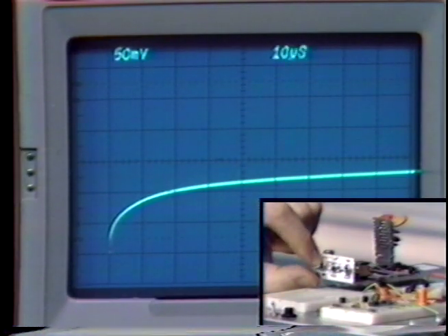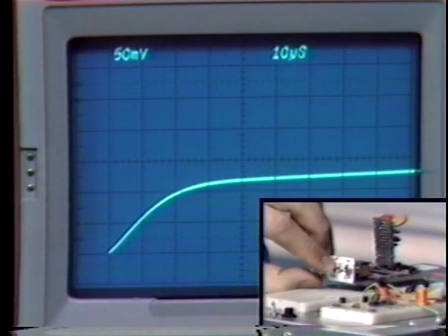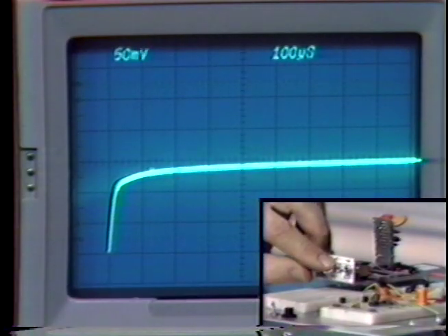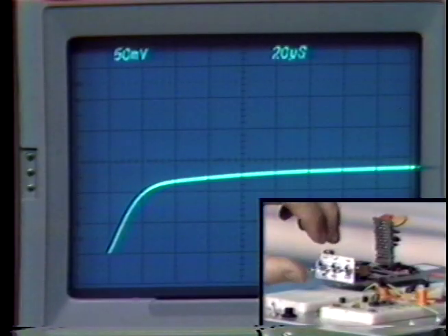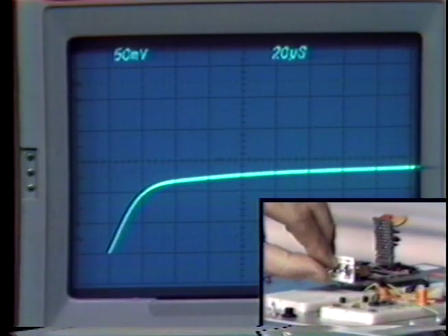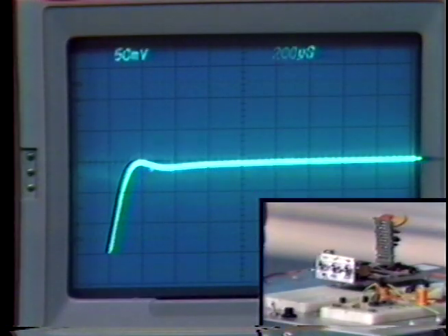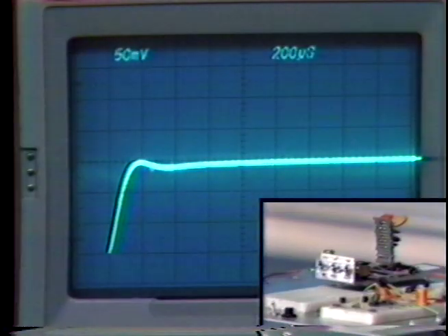But now let's go to 100 kilohertz. And this was a case where we were beginning to get measurable, significant overshoot when we used 1 over S compensation. Here things are still very well behaved. In fact, we really can't discern any overshoot. A little ripple, but we really don't see any overshoot. Let's move the pole back to 10 kilohertz. Getting a little bit of overshoot, but a very, very well-behaved response.